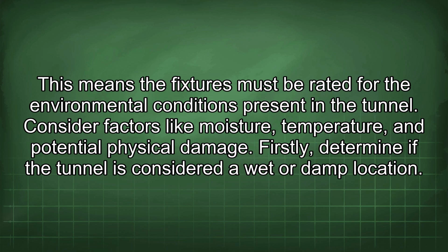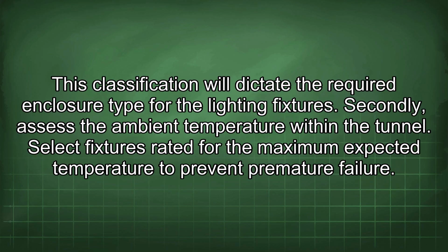Consider factors like moisture, temperature, and potential physical damage. Firstly, determine if the tunnel is considered a wet or damp location. This classification will dictate the required enclosure type for the lighting fixtures. Secondly, assess the ambient temperature within the tunnel. Select fixtures rated for the maximum expected temperature to prevent premature failure.